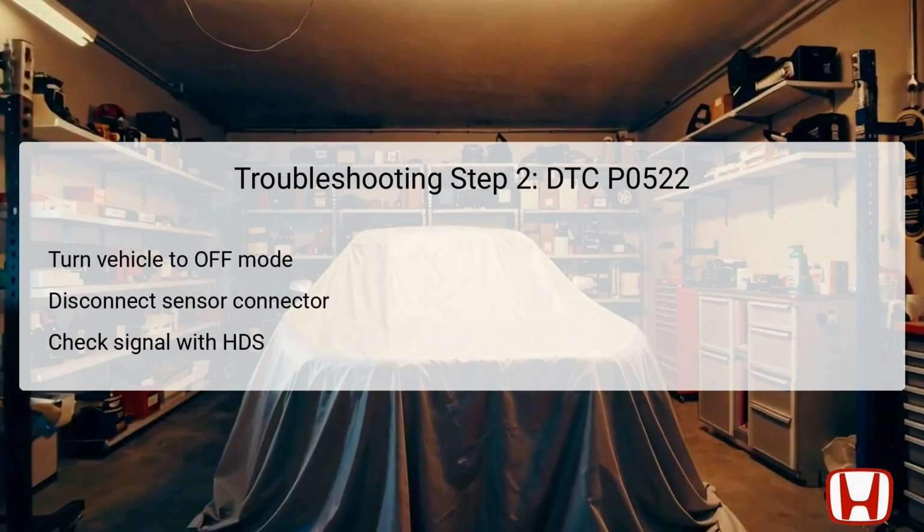When proceeding to the second troubleshooting step, start by turning the vehicle to the off mode. Disconnect the rocker arm oil pressure sensor's 3P connector. Next, switch the vehicle back to the on mode and again utilize the Auto Diagnostics system, HDS, to check the current conditions of the rocker arm oil pressure sensor.